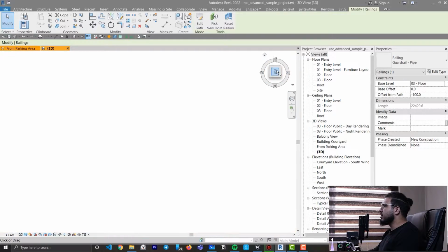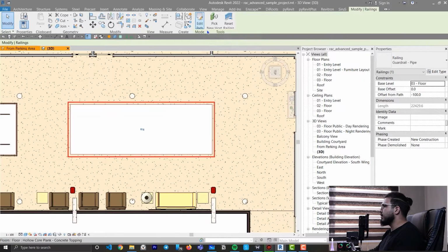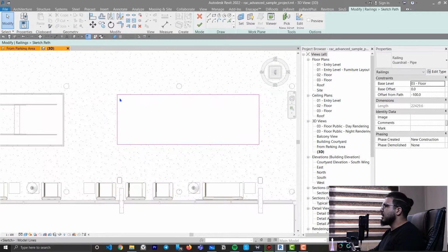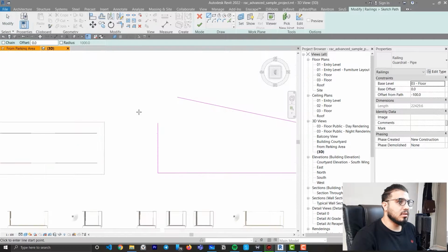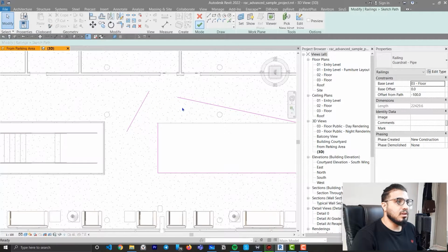And that's the way that you can create sketches. And also there are some limitations. For example, let's go to the edit sketch and let's bring it in here. You can have a continuous line, but you can't have multiple loops in the same rail. So that's the point. For example, if I create another path in here, it doesn't work, and it will tell you that you can't have multiple loops in the same rail.